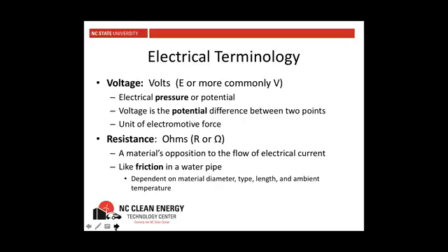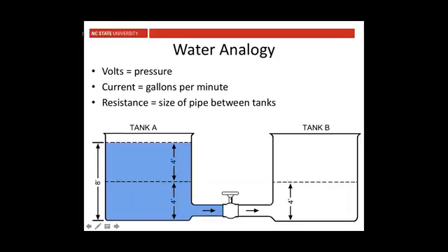And so when we're building PV systems, we're going to try and have the least resistance as possible because this friction makes us lose power. It turns power into heat, and that's what we want to avoid. We want to keep all the power we're making with our PV systems. So we want to have low resistance conductors, low resistance systems. We're going to keep the resistance as low as we possibly can when we design systems.